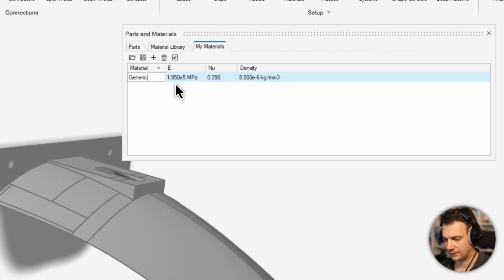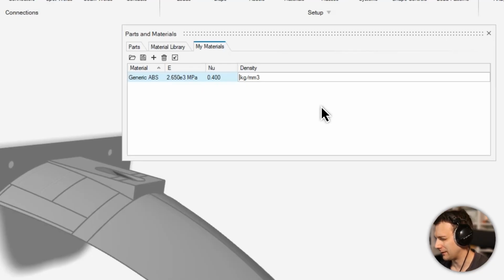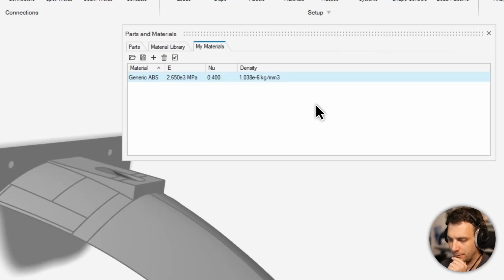So generic ABS. The Young's modulus is 2650 megapascals. Then the Poisson ratio is unitless and has a value of 0.4. And then here you have to be careful. The density is 1.038 to the power of -9 tons per cubic millimeter, but here we have kilograms, so we can say E-6 kilograms per...